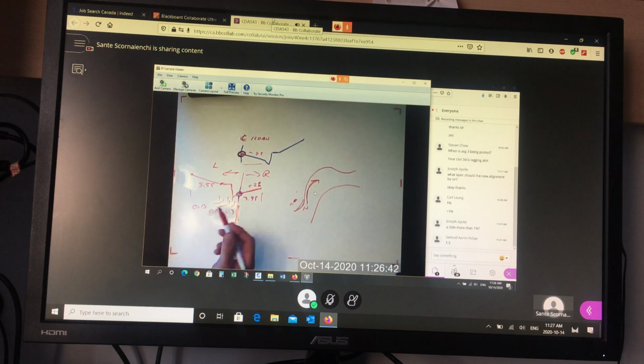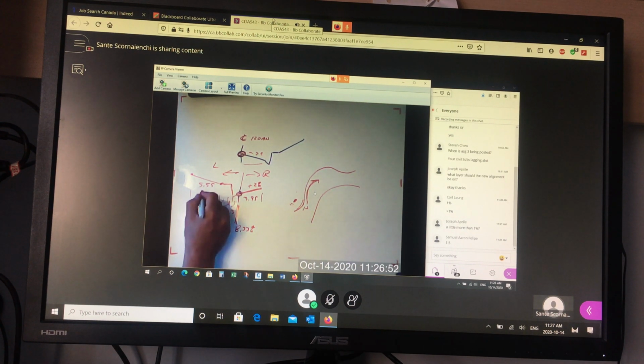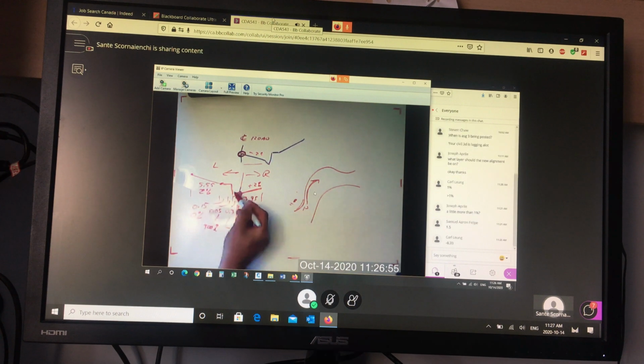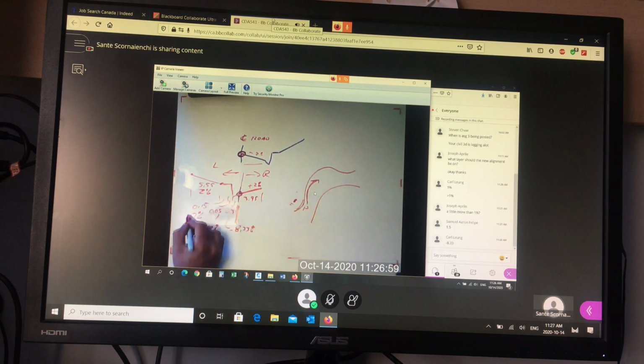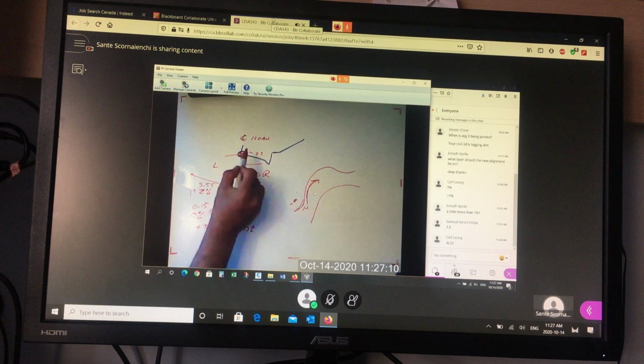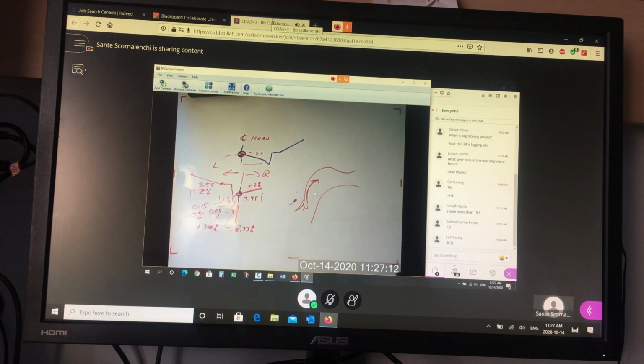And then the corresponding slopes. This one was 8.33%. This one was 300%, and this one was 0%, and this one was 2%. Okay? And away from center, this one's negative, this one's positive, this one's 0 is 0, and this one is also positive. Yeah, so you remember these numbers. So it's the same geometry, but I'm building it a little bit differently because my reference point is not the center of the road, but the gutter point, with the boulevard on the left side.